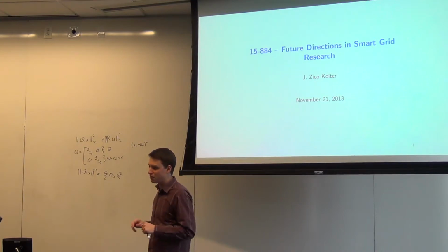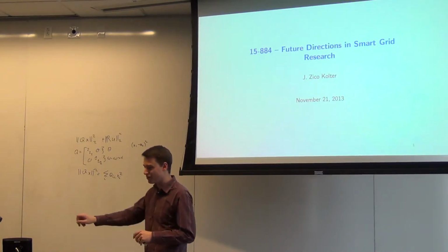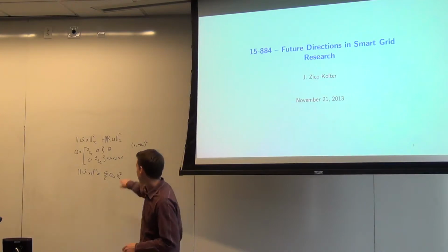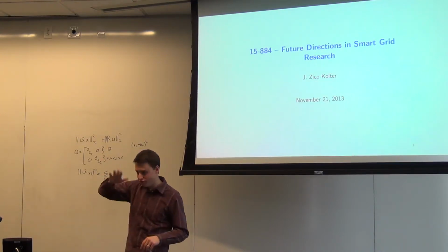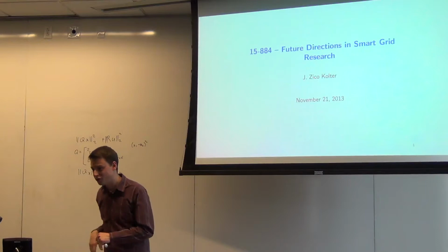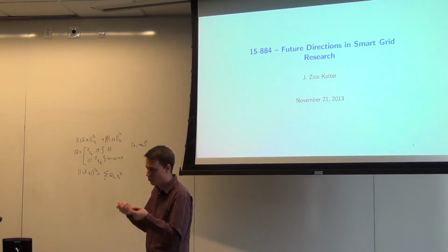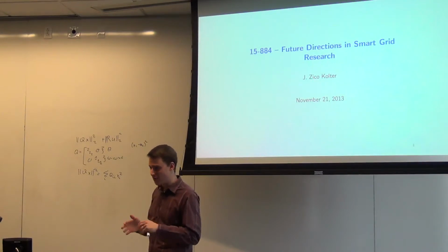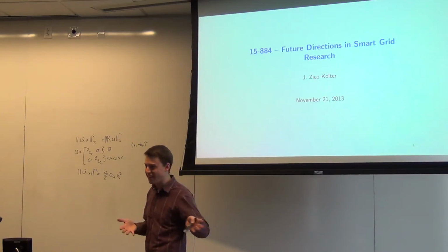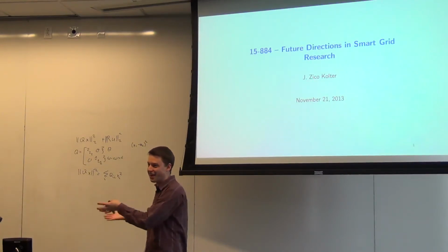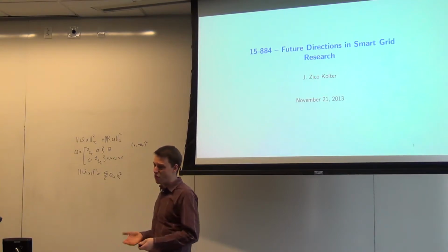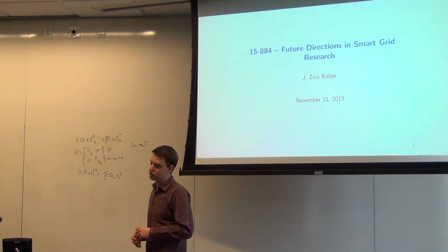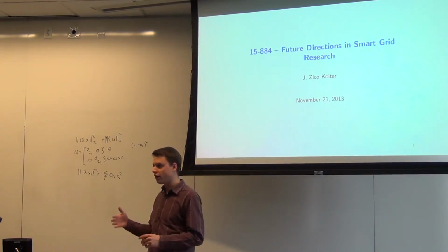But essentially it comes down to, if it looks wrong, you tweak the numbers a little bit, and hopefully it looks better. If your controls are just too big, they're flying around too much, you have too big of a magnitude, then you just increase the cost on R. Now, you can't play this game forever, right? There is a limit to the performance of the system. You can't just get perfect performance and have 0 control. You have to trade them off. But finding that trade-off is typically a lot easier than just guessing what the numbers are in the controller itself.